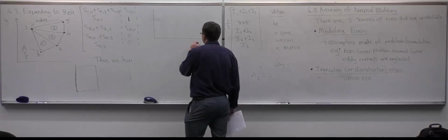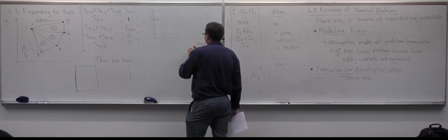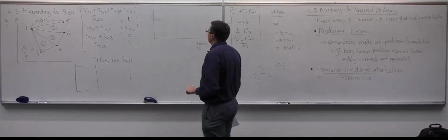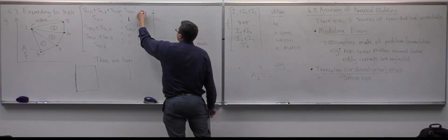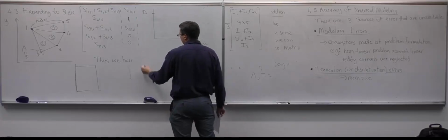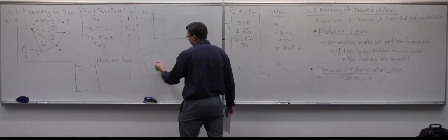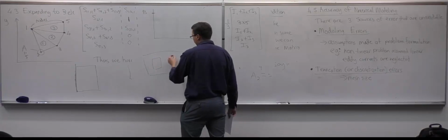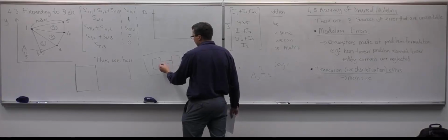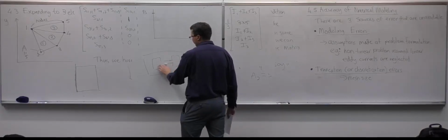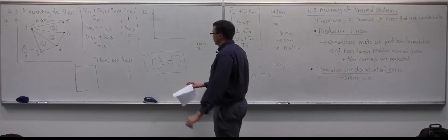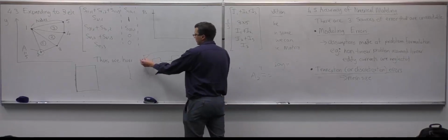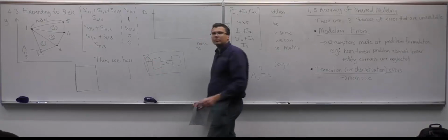You could, so you know the mesh number. Maybe the value you want is the magnetic flux density in the air gap of the device that we're looking at. So we're interested in the value of the magnetic flux density here. Now we divide this whole problem into lots of elements. But the question again is how many elements?